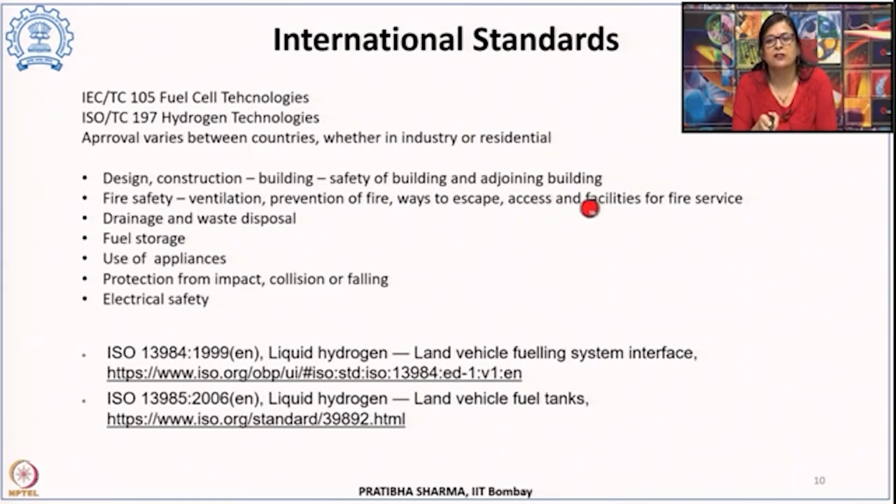is there an access or facilities for fire service being included, what are the drainage and waste disposal methods used, where is the fuel storage being considered, what appliances are being used at that place, protection from any sort of impact, collision or falling, and then the electrical safety. So, while designing such buildings wherein hydrogen technologies or equipment will be used, the standards need to be followed.